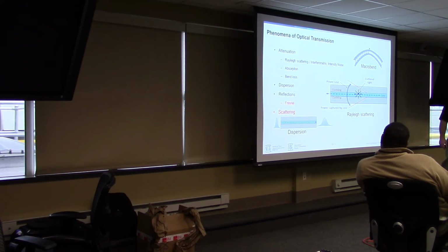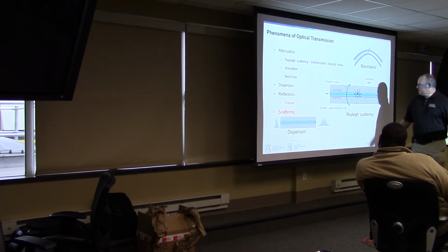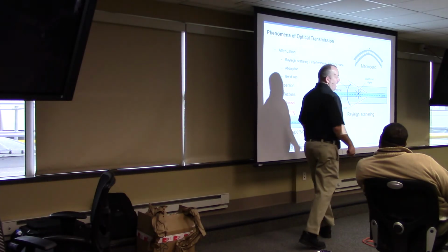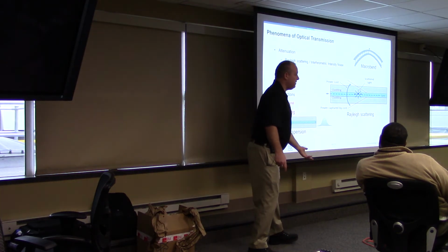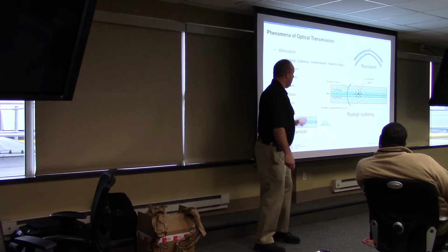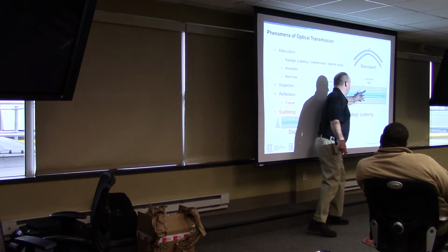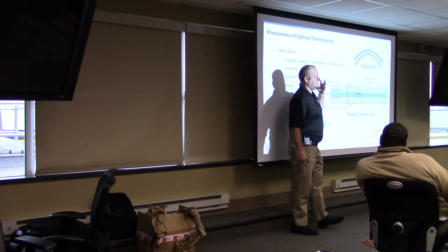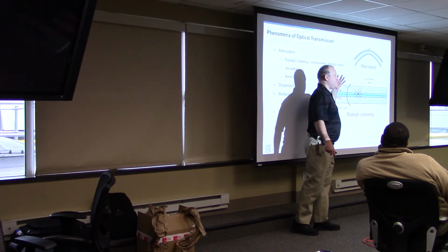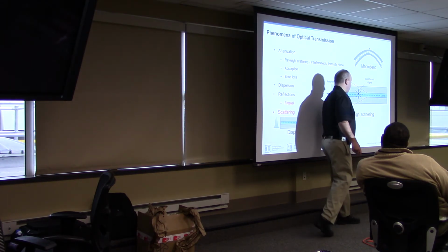Well, I only rubbed it off on my shirt a couple times, but I could have scratched it. Yeah. So that's what we're showing there, scattered light. And the interesting thing about an OTDR, you send light, and what happens when it hits those imperfections, light comes back, and we measure that light. And then that tells us where there are imperfections in the fiber path.